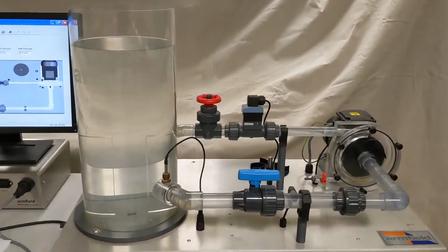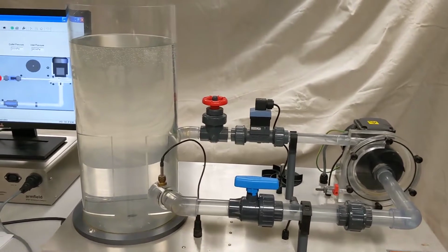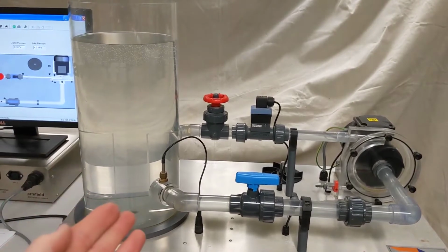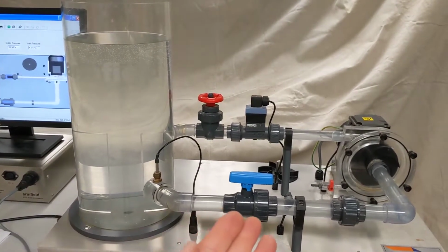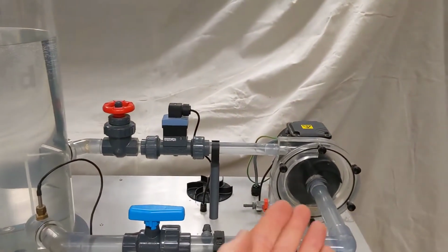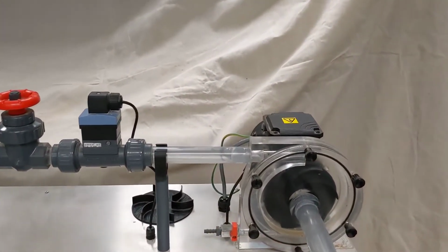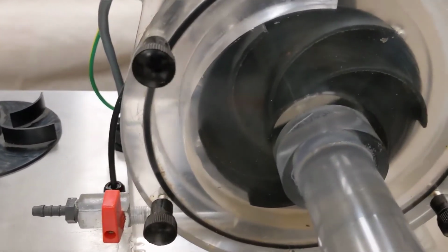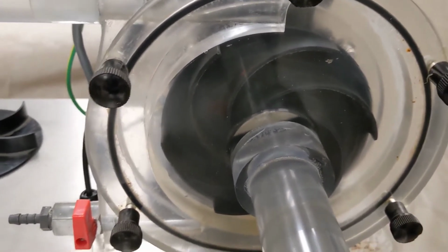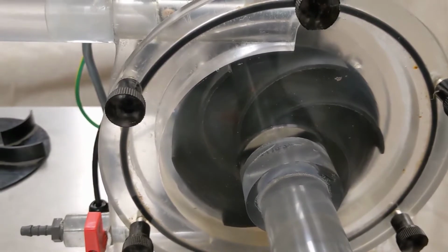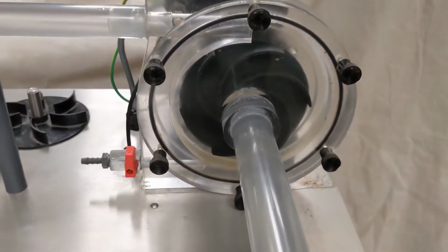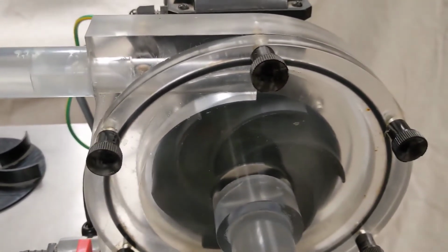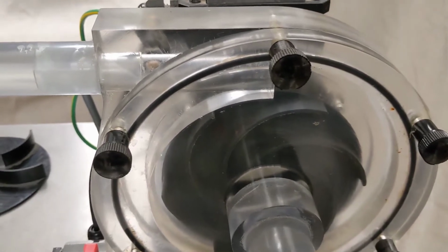Just to give us an overview here, we've got the tank of water right here that is going to be our reservoir. There's a pipe leading out of it, goes through a valve, down here, through a bend, and then this is actually the pump. So I'm going to get a little closer there so you can see what we call the pump impeller. That is the part with the vanes on it. And as that turns, it pushes the water away from the center. So you can see the inlet pipe comes into the center of that. And then those vanes push the water to the outside. And then the water has nowhere else to go except out this exit pipe.